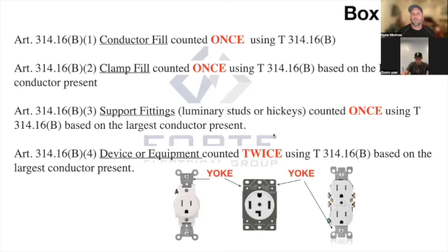Let's see where we're at. So what you do there, you just add all that up. Depending on the question, it's going to give you something in there. They change it all the time. It's usually number 12, so it's going to be a 2.25. And then they're going to throw a receptacle in there, or a switch, or a snap switch in the box.